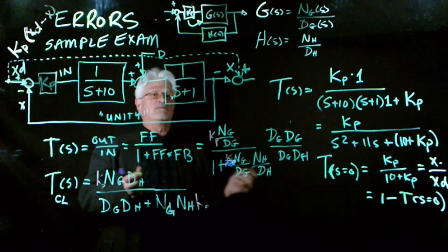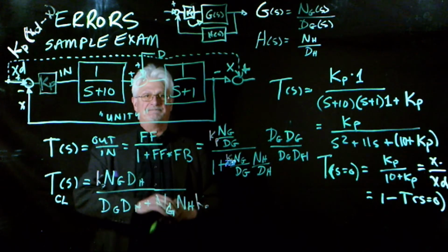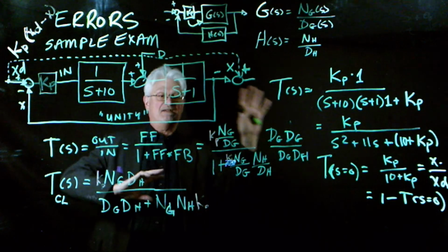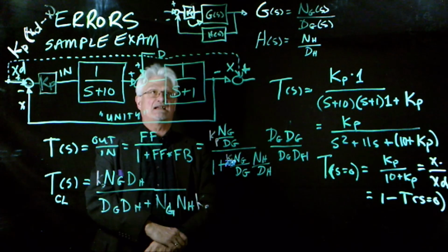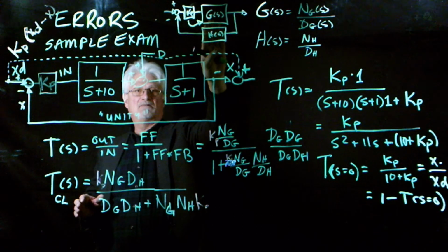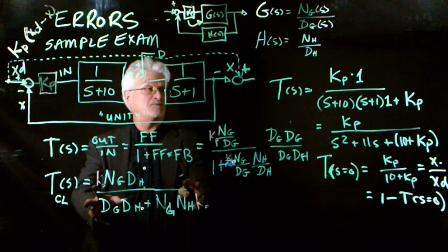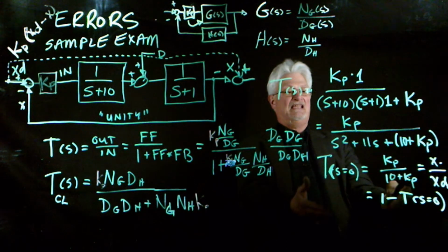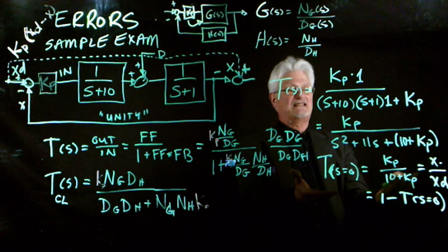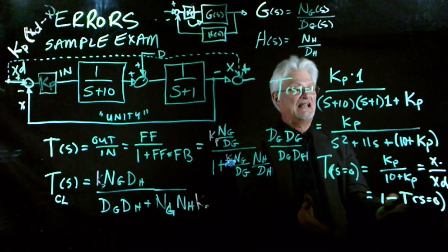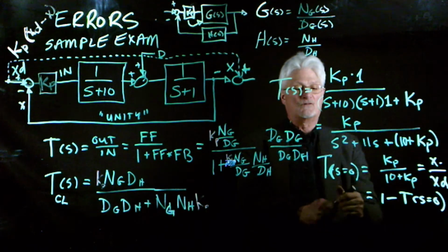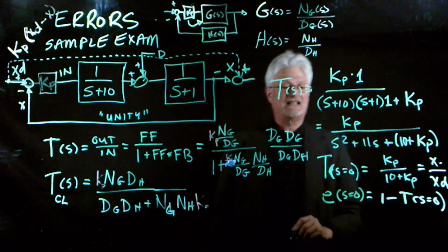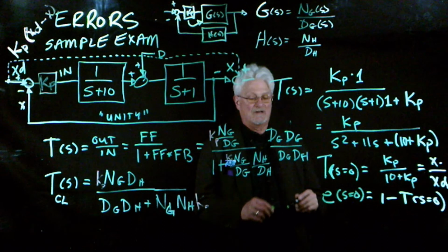So there's a number of different formulas that they go through in there. I'm going to go into some of the formulas, but I want to make sure that we all understand this part of it first. Some block diagrams, the block diagram reduction, the overall transfer function for our system, and then also what the steady state gain for the system is and how the steady state gain differs from the steady state error. Right? The steady state error is 1 minus that.